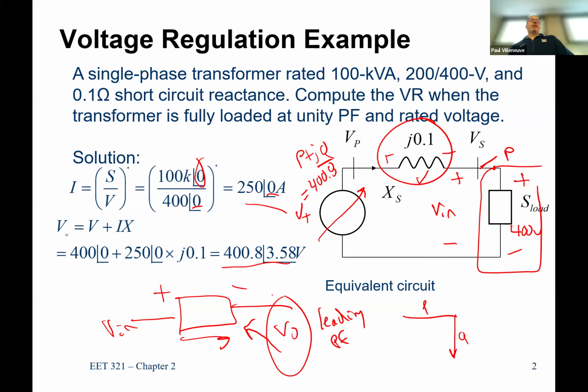Most loads operate at a lagging power factor. That's why I said it should always be higher. But if you have a capacitive load, like if you're at a substation and you have a cap bank, then it could have a leading power factor. But every industrial facility here operates at a lagging power factor. It just wouldn't make sense to go leading. Good question.